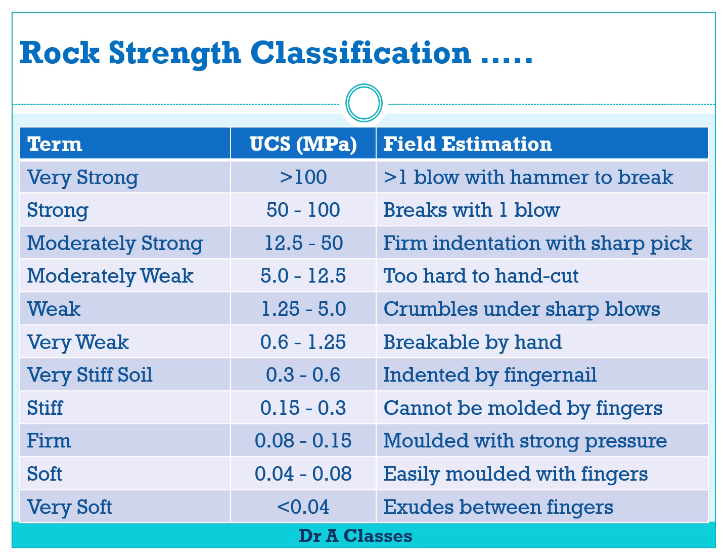Moderately strong, 5 to 25 MPa, requires considerable force to break, includes fine-grained sandstone and weathered granite. Strong, 25 to 50 megapascals, hard to break manually, includes most intact limestone and some igneous rocks. Very strong, 50 to 100 MPa, extremely difficult to break, includes dense igneous and metamorphic rocks like basalt and gneiss. Extremely strong, more than 100 MPa, practically unbreakable by hand tools, including unweathered quartzite and granite.